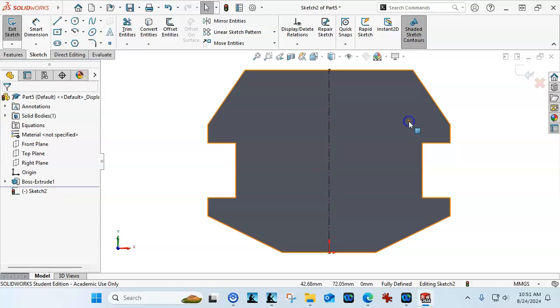I don't know that I need to have it be an infinite length. I could go either way on this one. It doesn't have to be. So we'll just put that in there. So we have the spline. The style spline, again, it kind of does an extension, and your handles are at the end of those extensions, and then an equation-driven curve you can put in algebraic or trigonometric functions and have it create from those equations.